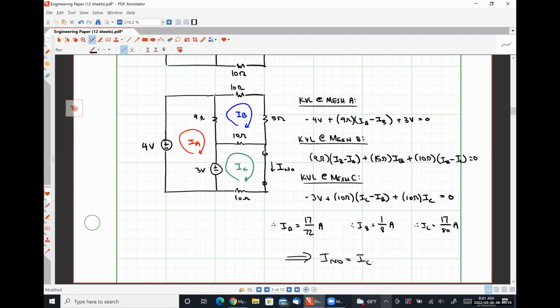On some it is, and on some it isn't for whatever reason. But typically speaking, let's say if your positive polarity of your Thevenin voltage is on top, then your Norton current should be pointed down. And let's say if your Thevenin voltage positive polarity was on the right, then your Norton current should be directed to the left. Yeah. But in the problems that I write, I try to explicitly tell you which one.